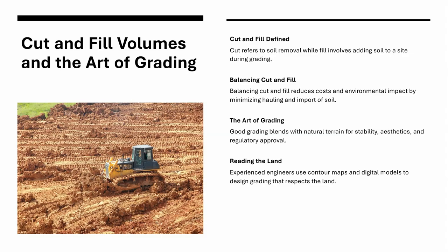It's costly, it's disruptive. If you have too much fill, you're having to bring in too much soil, and that is also going to be costly and sometimes environmentally unstable. Good grading design strives for a balanced site, where cut roughly equals fill. Your grading groups allow engineers to calculate this balance with precision, and minimizing that cut-fill ratio is what we're looking for.